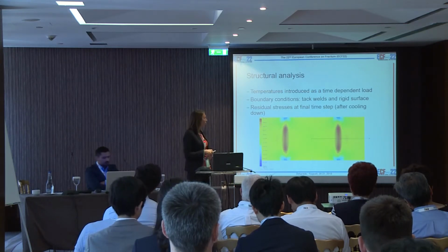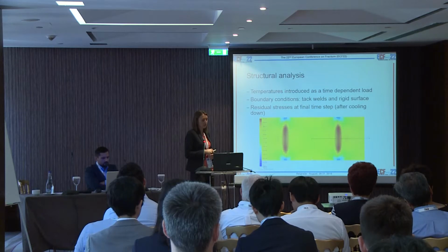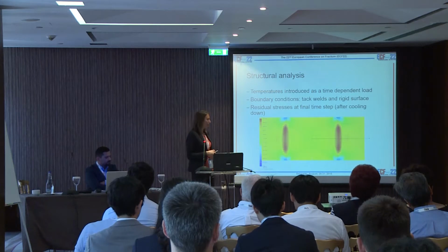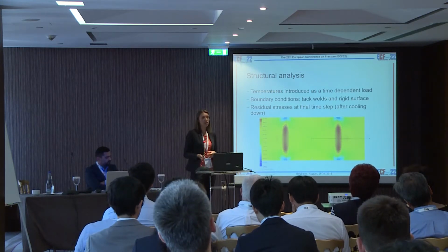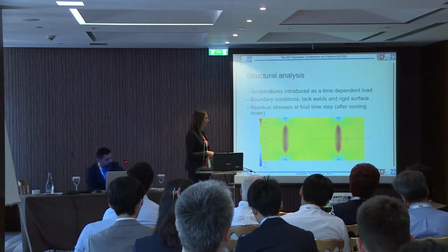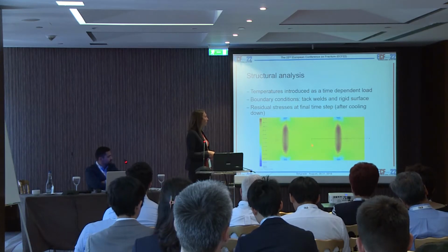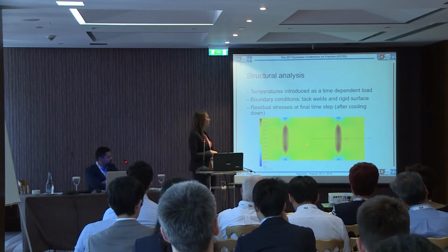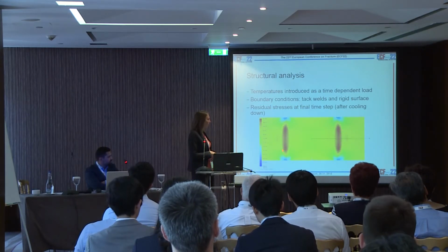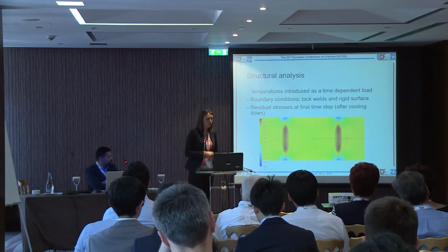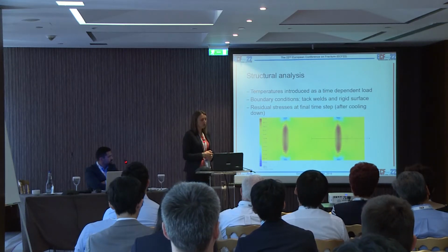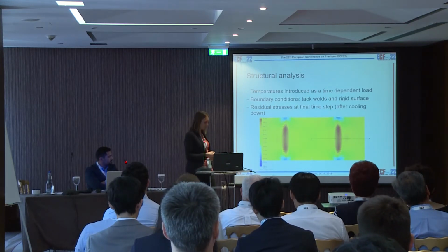These are the results of the residual stresses in the transverse direction. This is the direction which is perpendicular to the welding line. And this is the final time step. So after cooling down, after the welding, you can see that here there are tensile yield stresses present. In the middle, we have a compressive residual stress of about 45 megapascals, and near the sides, the residual stress is close to zero. We always look at the middle section for the results in order to avoid any interference of the boundary conditions.